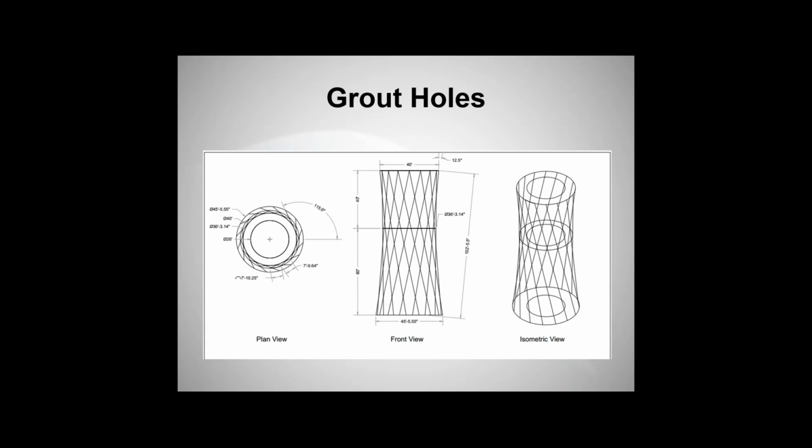But here's what you've got to realize whenever you lay those holes out. Let me describe this. This inner circle is the excavation of the shaft, which I'm tracing there. You start a little bit further outside the shaft. As you drill these holes, you will come to some minimum distance from the neat excavation line of the shaft, and as you extend past that point, you get further and further away from the shaft. If you see this outside circle that I'm tracing here, eventually you get too far away from the shaft, so that your holes are no longer at that 7.5 to 10 foot spacing.